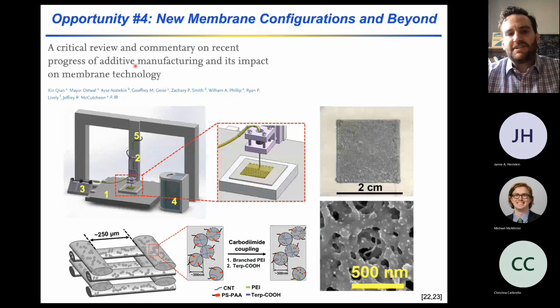The second to last thing I'll mention is that I think this phase separation technique can be merged with additive manufacturing in order to create structures with organization across multiple length scales. And so if you think about creating adsorptive membranes, you could imagine 3D printing your casting solution in a humid environment. And so the 3D printing is allowing you to control the micro scale structure, where we have this wood pile structure generated by the printing algorithm.